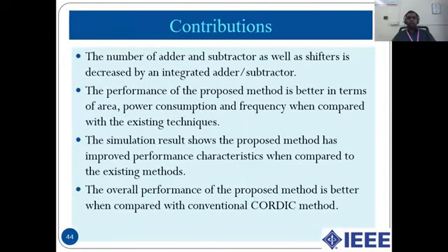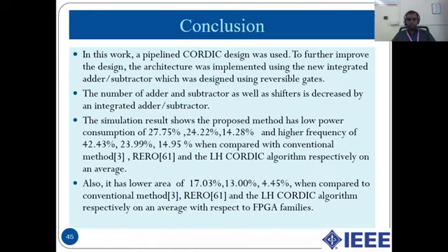And the main contributions of our paper are that the number of adders and subtractors as well as shifters is decreased by this integrator adder and subtractor, and the performance of the proposed method is better in terms of area, power consumption, and frequency when compared with the existing techniques. The simulation results also show that the proposed method has improved performance characteristics when compared to these existing methods, and the overall performance of the proposed method is better when compared to the conventional CORDIC method.